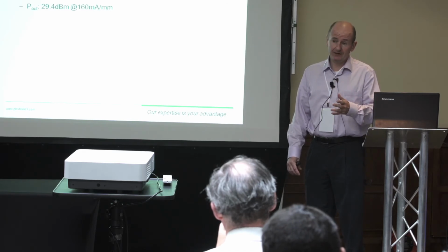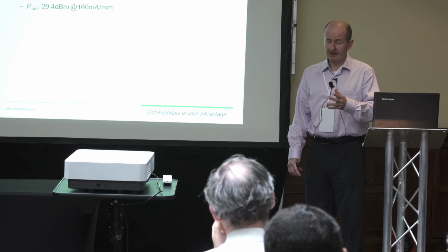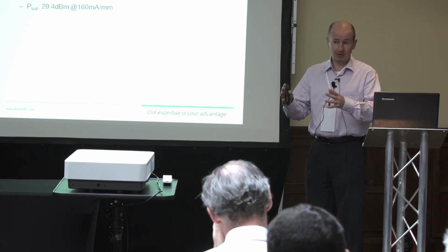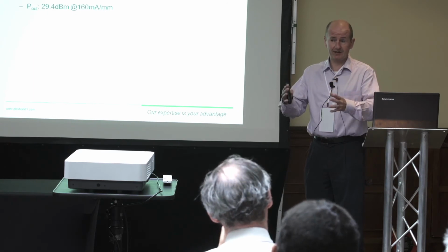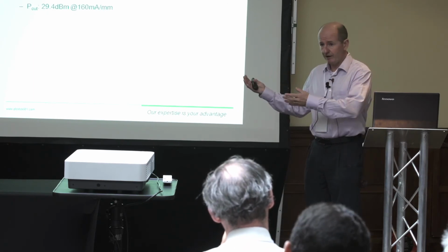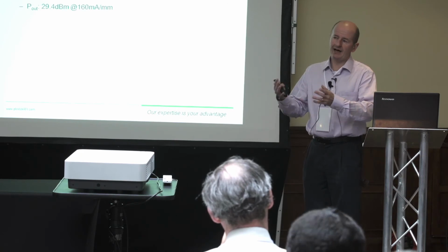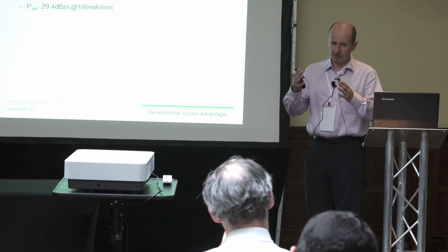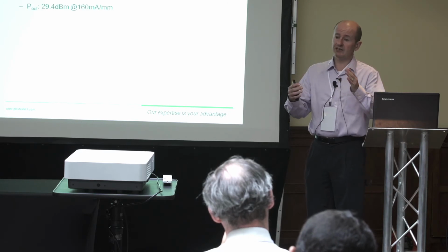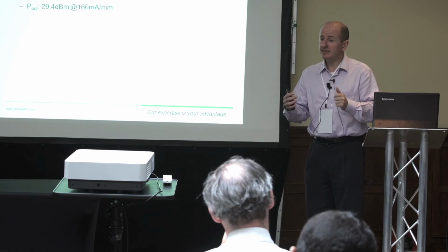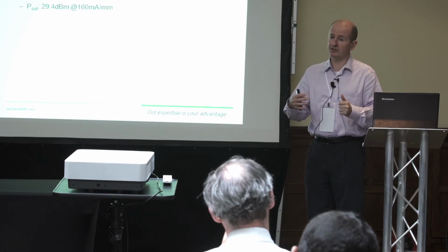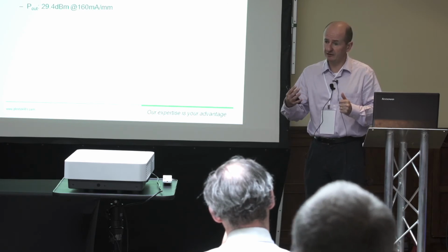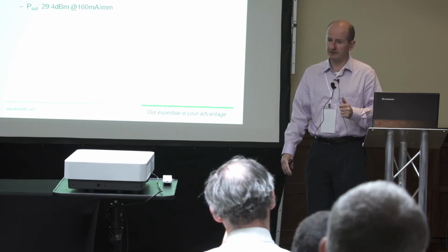You also need a lot more work with your modelling. And again, I'm going to re-emphasize what Rob said earlier. You've got to get your modelling right. If your model's not right, you can design yourself a lovely circuit, and when you make it, it'll be miles away. There's a lot of work involved to get the model of the GaN transistor right, because that soft compression characteristic is a little bit different from all the conventional models that were originally developed for FET-based technologies and PHEMT-based technologies, which have a much sharper characteristic.